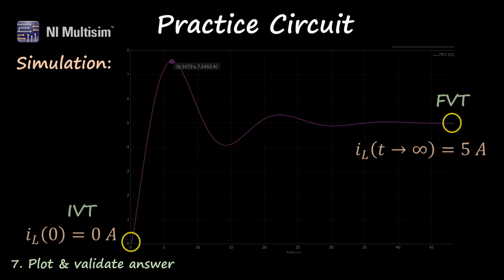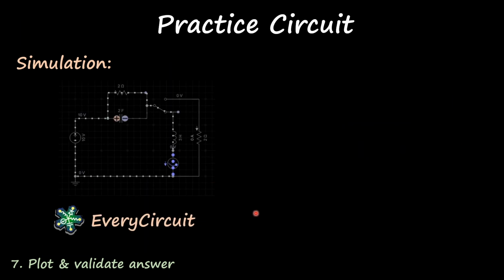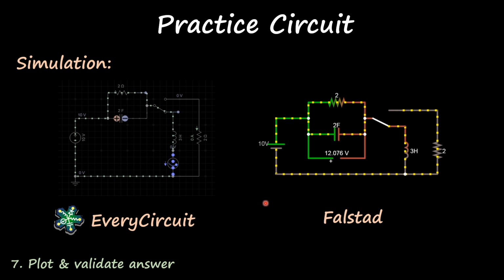You can use other simulators. You can use, for example, EveryCircuit or Falstad. Just a heads up that I should have put a ground, the reference point here. By default, I believe it's here, but I highly recommend all the time to have a reference point. But I would say the challenge with these interactive simulators is that the window of simulation is very short, around probably 1 to 2 seconds on Falstad, and probably 10-15 seconds on EveryCircuit, which makes it a little bit harder to see the overall answer. Let's just see some of those videos so you can get a grasp.